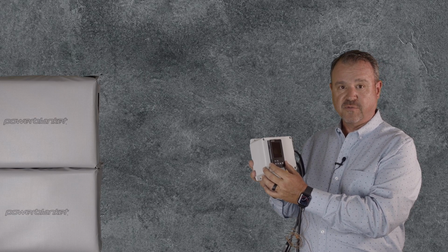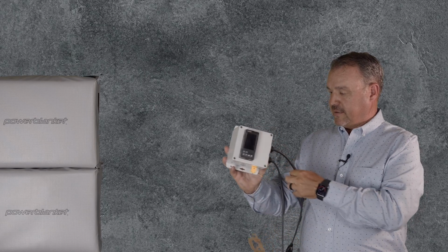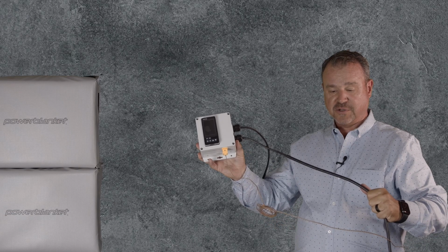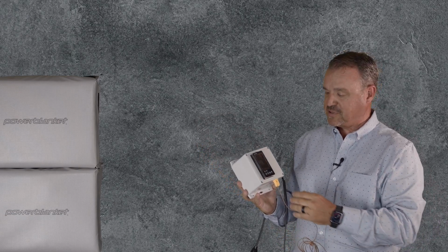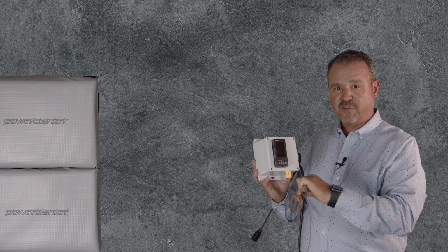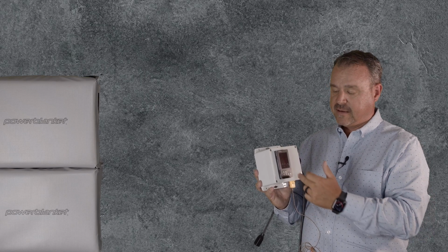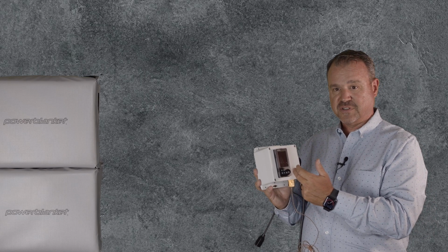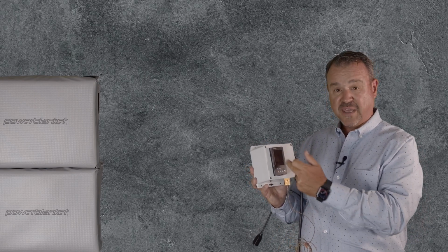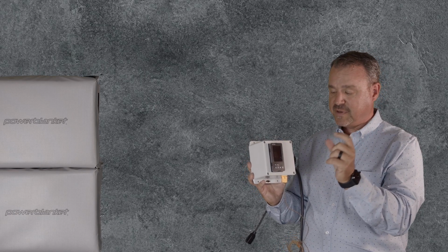Here we have an 8th DIN red line controller that has a thermocouple input and has a way for power to be applied to the unit and a way for power to go to the load. Again, just a really simple example. What's happening here inside this controller is it's receiving an input from this thermocouple at a sampling rate of multiple times per second. This controller can then take that temperature sensing reading from this thermocouple or RTD and make adjustments to the output to the heater over a very short period of time.